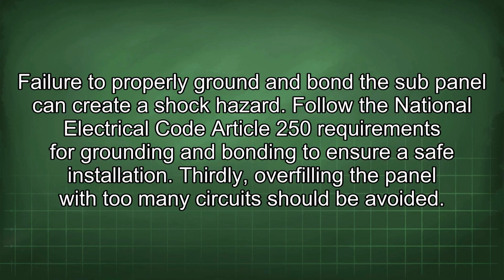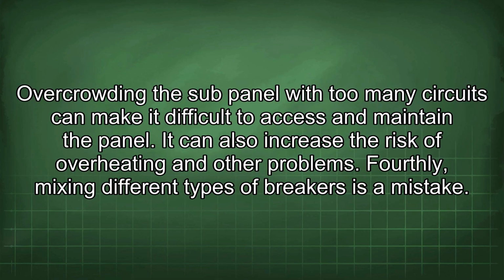Thirdly, overfilling the panel with too many circuits should be avoided. Overcrowding the sub-panel with too many circuits can make it difficult to access and maintain the panel. It can also increase the risk of overheating and other problems.